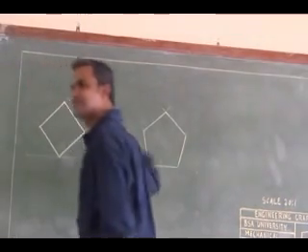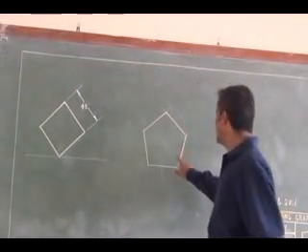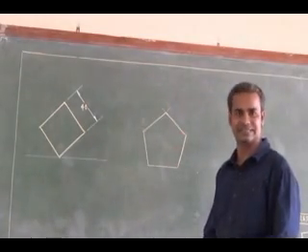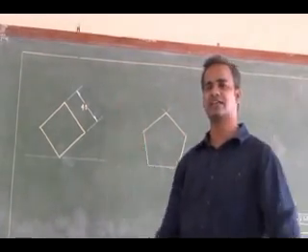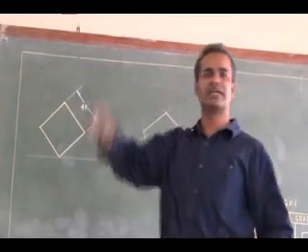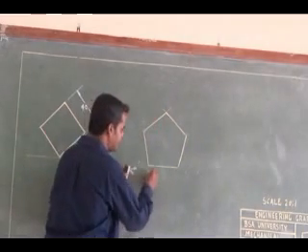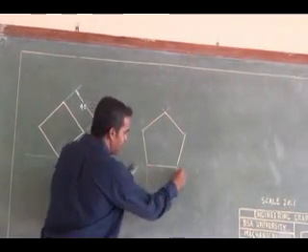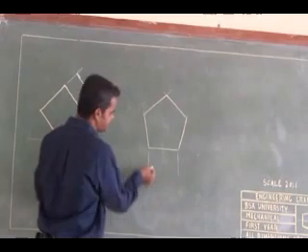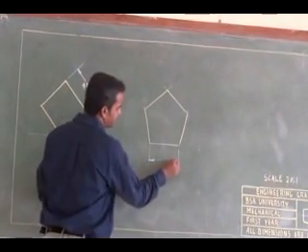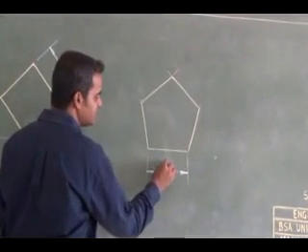These all come from a circle. So remember this is the way I can draw. One side is horizontal, and I can draw a pentagon like this. Using my drafter I can construct 3 sides, and using my compass I can construct another 2 sides. Then you can dimension this side. Fix your drafter parallel to this, then draw the extension lines, then draw the dimension line like this. Then this is the 30.